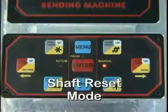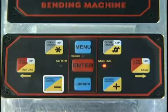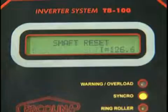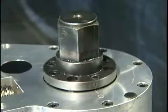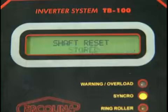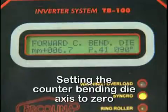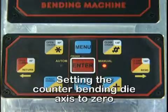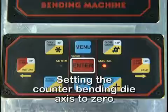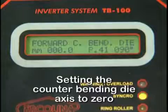For further adjustments, on the control panel depress Menu, then press the plus or minus key until the display reads Shaft Reset Mode. Depress Enter to select the Shaft Reset Mode. Depress the Return or Bend key until the 0 marks align, then depress Enter. The display should now read Shaft Reset Stored. To set the counter bending die axis to 0 on the display, depress Enter. Note, the bender will not cycle if the counter bending die axis is not at the 0 position. This 0-point adjustment accommodates various center formers and material sizes.